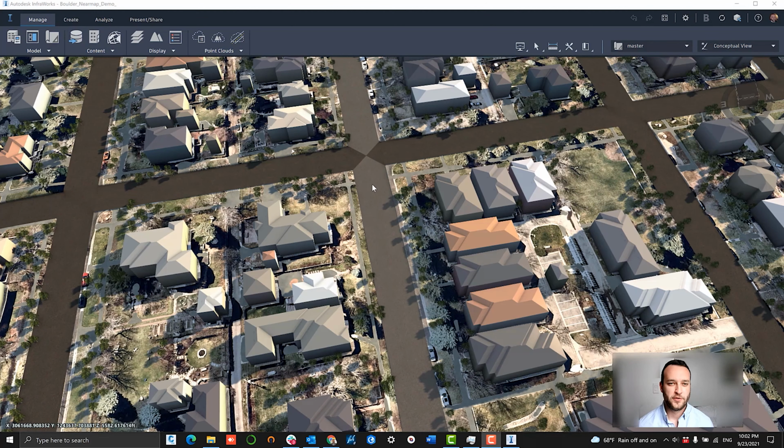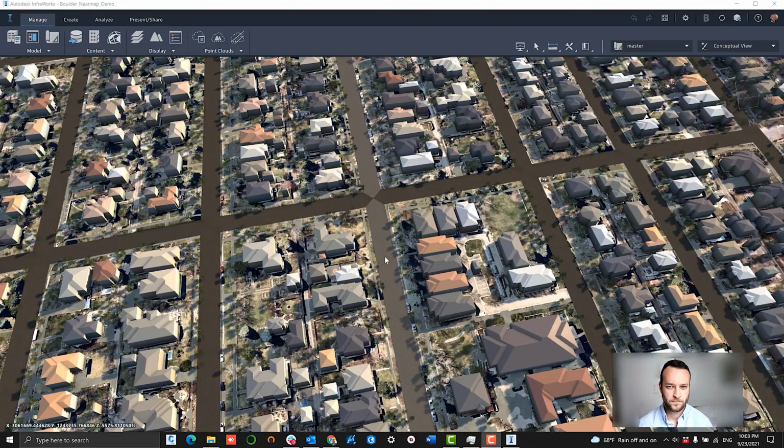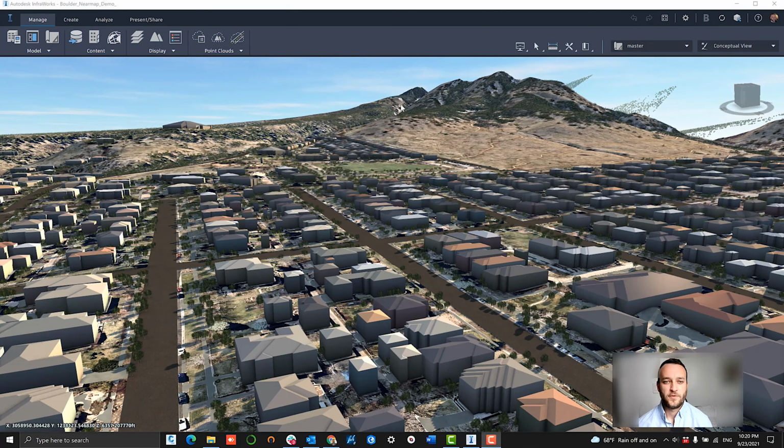Moving over to this aerial view, we can see that our concrete slab has been identified at the ground. We now have an InfraWorks object associated with it. We have our sidewalks. A lot of our driveways have been identified by the algorithm as being this material type. Again, adding that extra additional layer. All right, so that was just a handful of AI attributes that can be loaded as 3D objects within InfraWorks.